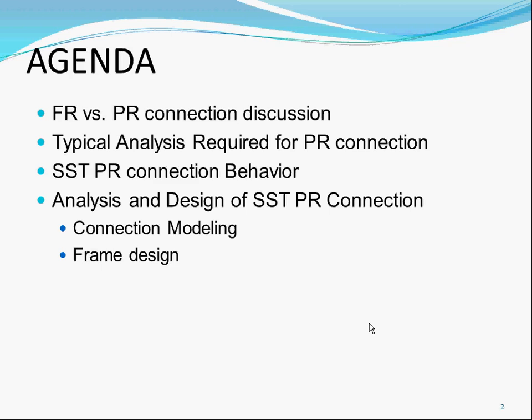Typically, when you do a moment frame connection and model it in SAP, people just stick in a line for a beam and a line for a column. Where it comes to the connection, they just connect it and don't release any shear or moment. So they just make a moment connection, and that's all they have to do. Because that's considered rigid, the connection has not much rotation due to bolt slip or whatever.